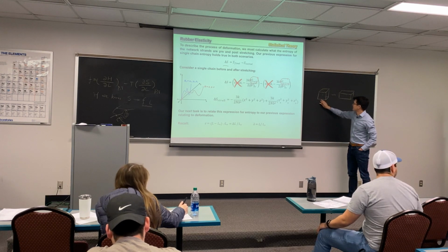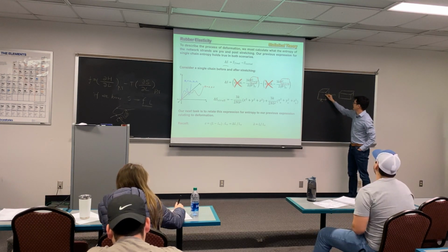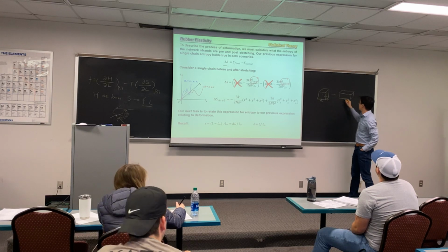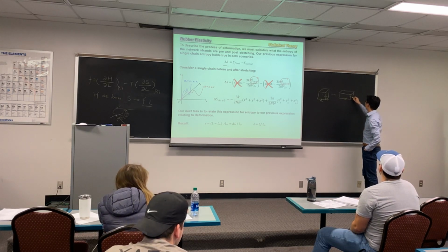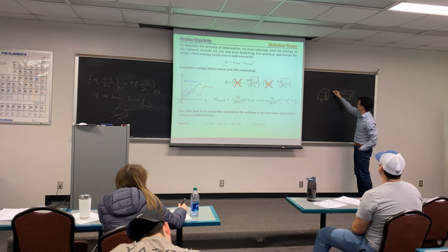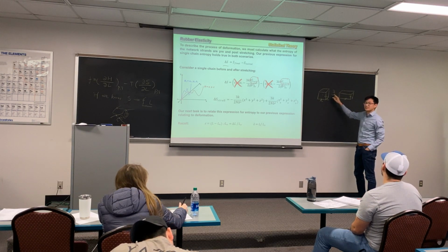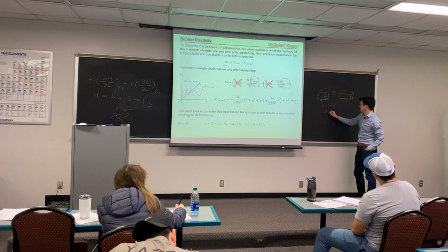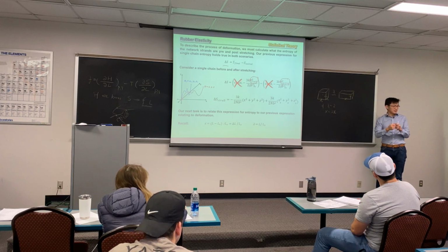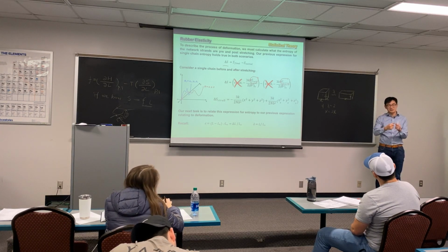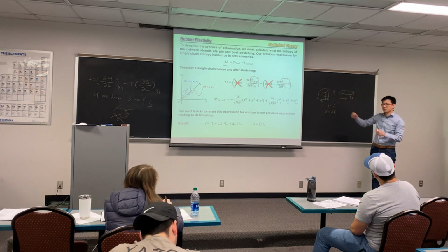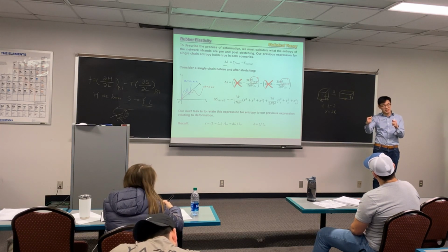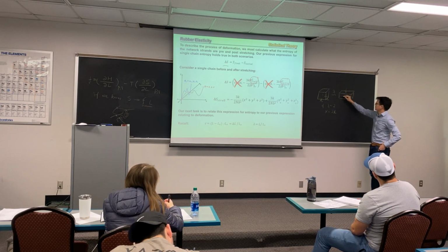So we know this is x0, z0, and y0. And this is our new x, z, and y. We know if we pull it at a lambda, let's assume lambda equals 2, that means your x will be twice of x0. If you have a rubber band or rubber cube and you pull it twice in the x direction, the other directions will contract.